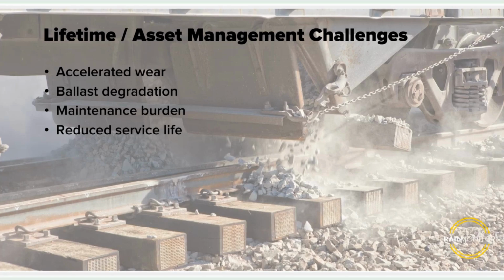There will be some maintenance burden, more frequent tamping, maybe also stone blowing and under sleeper stabilization. So these are all things that are being challenged by having these voids.